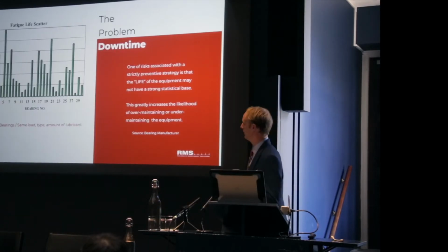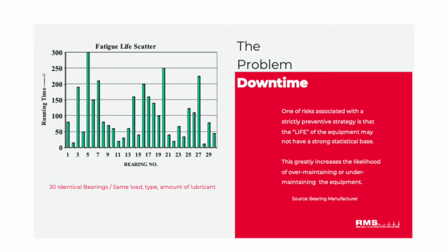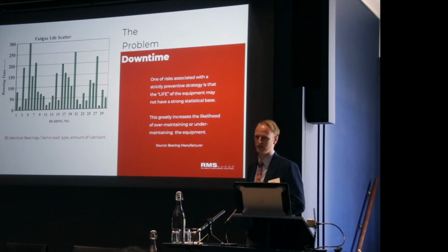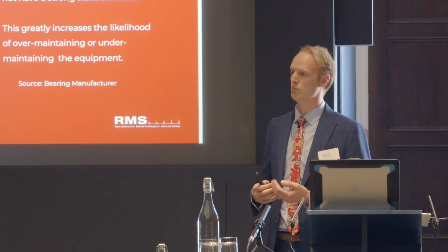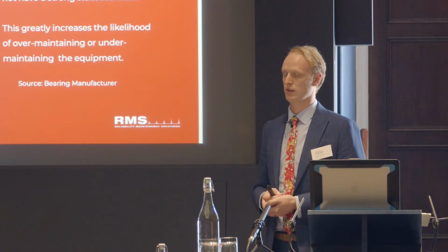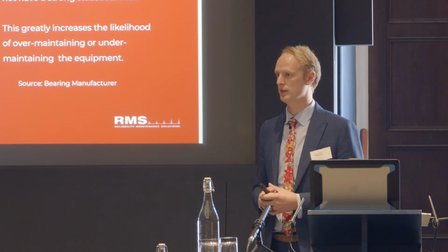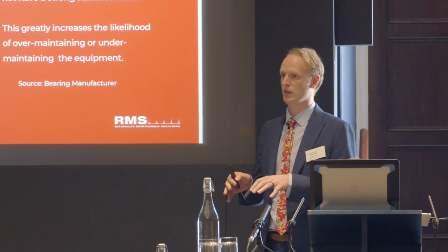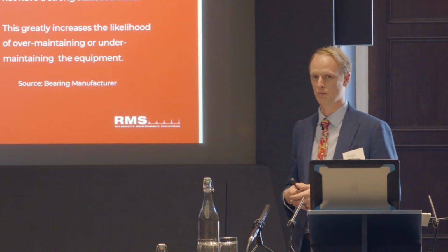Typically, you probably hear a lot about preventative maintenance and calendar-based maintenance as being a buzzword at the moment in many different industries. But some time ago in the 40s, during the war, the RAF established that this was causing more failures on their machines than if they were to just run them to failure. So human induced problems come from planned and preventative tasks.